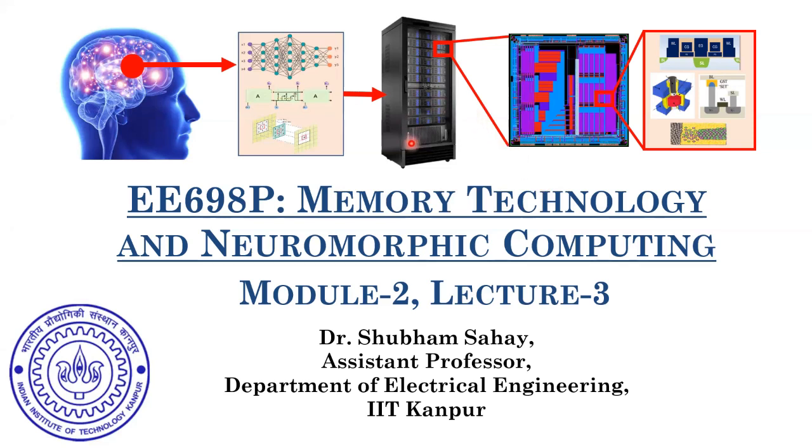So with that information, in this lecture, we would be looking at the read-write conflict in an SRAM cell. We would also be looking at some other SRAM cell architectures. As I already told you, apart from the 6T cell, which is the industry standard right now, we also have a 4T cell, a 5T cell, a 7T cell, an 8T cell, going up to 16T to 17T, depending upon the application that we are looking at. For radiation hardness, people go for the 17T SRAM cell as well, to provide immunity against single event upsets and so on.